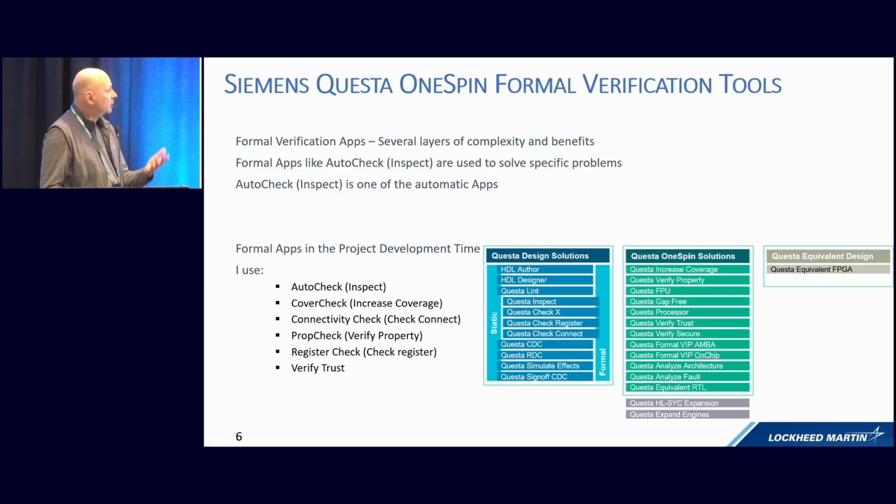So I use AutoCheck, CoverCheck, Connectivity Check, PropCheck, very little Register Check in the past, and Verify Trust. All these tools come either from classic Mentor 0-In or from OneSpin tools that you've seen. They are now integrated with Questa formal verification.